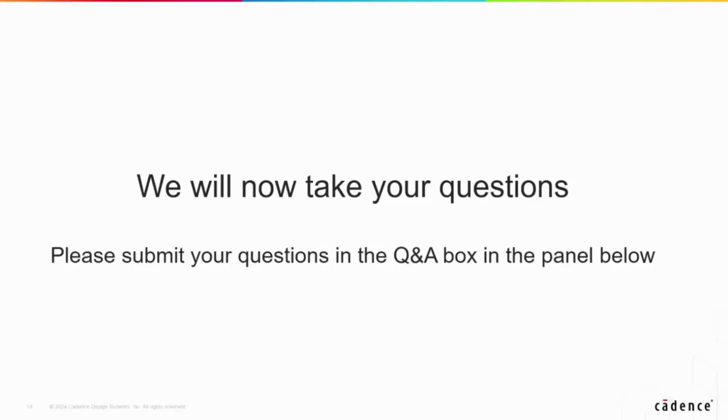They mentioned component/element models. I think maybe there's a chance, because a lot of times when we get into the 3D extraction world, people are wondering about detailed models for 3D components. Could be inductors, capacitors, maybe even a mechanical connector that would be connected to a PCB or a package, potentially even a socket that you would want to model.